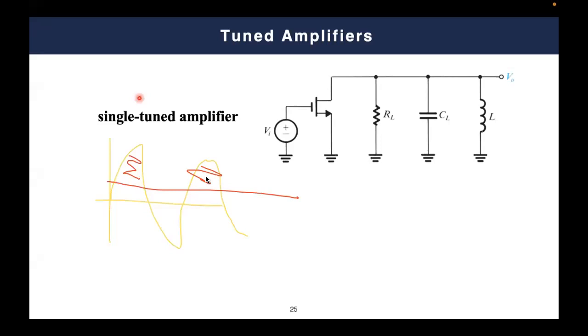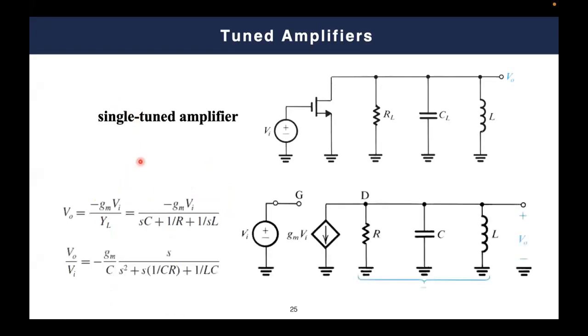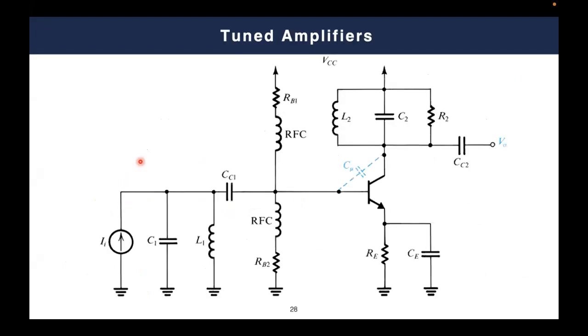That's why we need to DC bias the input voltage with a certain DC bias that allows a full 360 degree operation of your input signal, to ensure that all the time the gate voltage is above the threshold voltage, and you ensure this full operation. Usually, if you remember, my dear students, we used to use this. Let me show it to you. Yes, here. This resistance, if you remember, this potential divider.